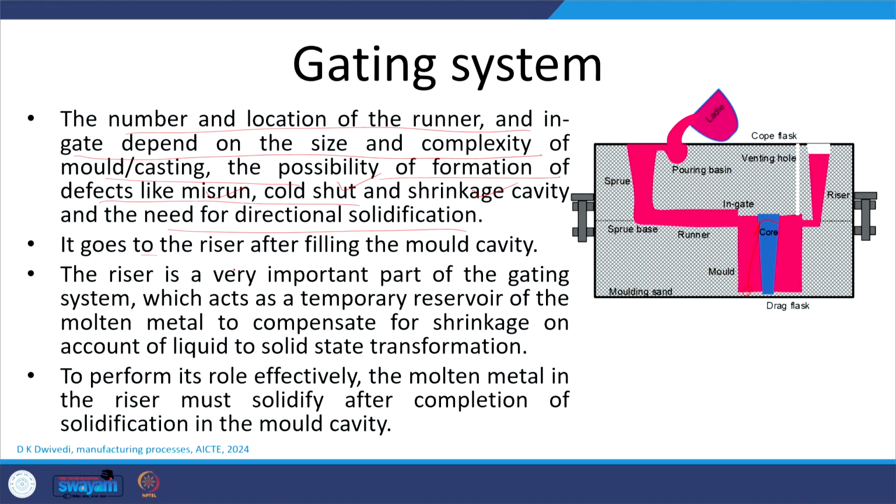So, molten metal, after filling the mold cavity, goes to the riser. The riser is an important part of the gating system, which acts as a temporary reservoir of molten metal to compensate for the shrinkage on account of the liquid to solid transformation.